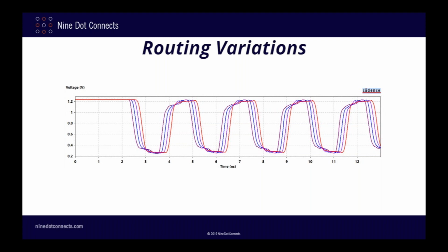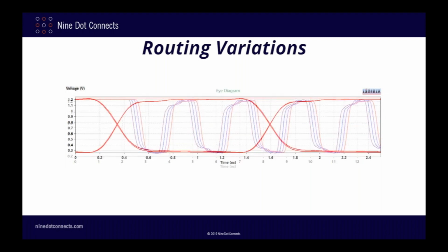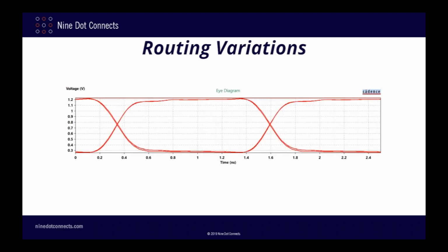The 4 waveforms represent the signals at each of the 4 memory devices. You can clearly see the time shift caused by the trace distance between the chips. And here is the eye diagram, but only for the signal to the last memory chip in the chain. It also looks pretty much like an ideal eye diagram.